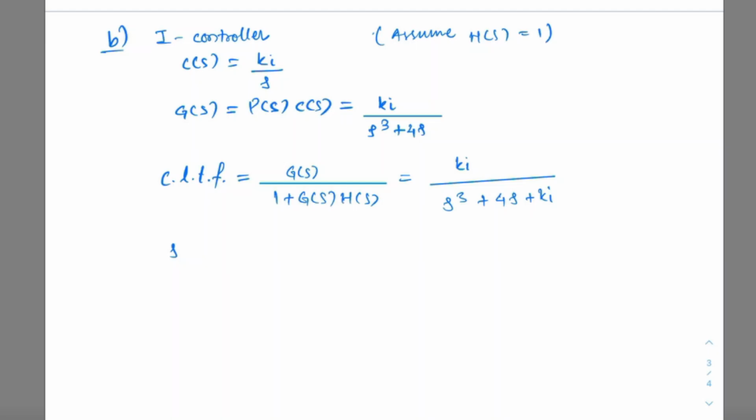So in case you are supposed to figure out a search problem, in which you don't know what Kp and Kd values should be chosen, and you have a plethora of objectives to satisfy, you can restrict your search region to the stable region itself, so that all the solutions you are obtaining are essentially stable solutions.